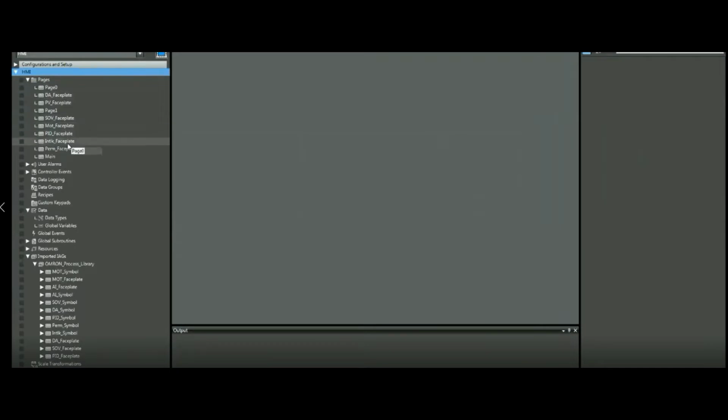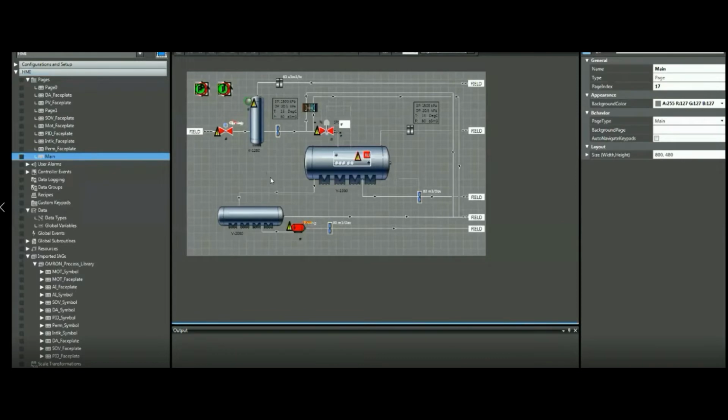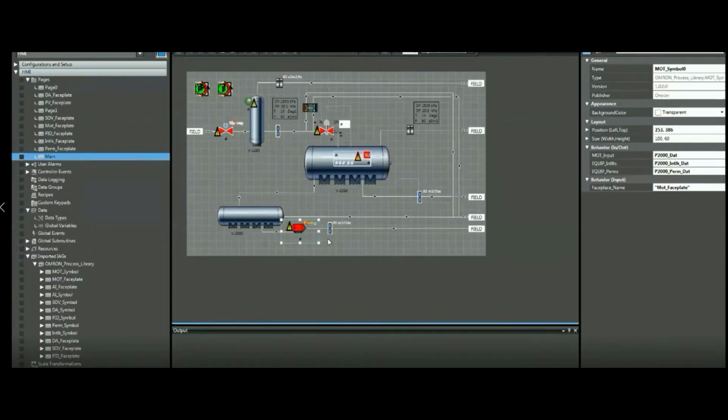Similar to the PLC, for the HMI you're going to find a few screens. Some of them are templates for the particular object. If we go to the main window here, you can see we have a few objects. The one we're interested in for the purpose of this video is this pump in here. And as we can see, it's all linked and it's all good to go.